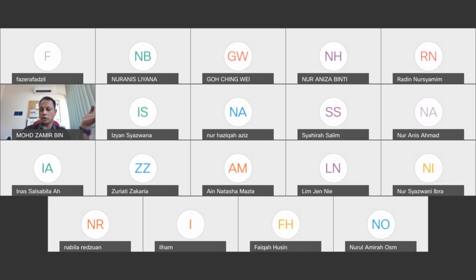So yield engineers will normally have frequent meetings. So the meeting is a platform to highlight what is the ongoing problem, including the yield problem on certain technologies, certain devices. So that's where the yield engineer chases process engineers or equipment engineers in charge of that particular process or equipment to look into the problem within certain time frame. So then yield engineer, they can follow closely like what's the status of your findings on circular defect problem in your tail track equipment, maybe something like that.